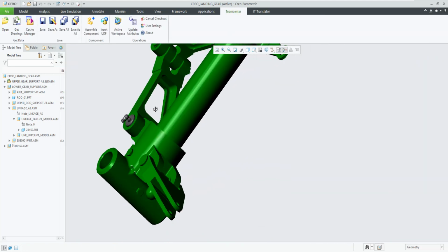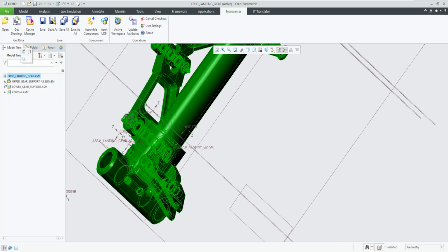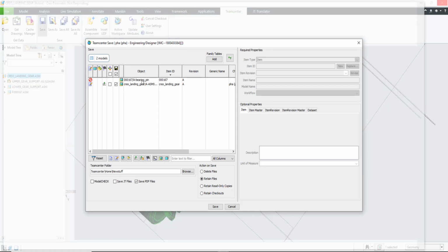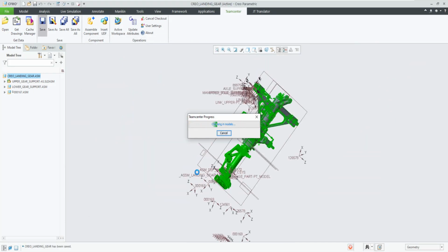To summarize, at this point we have a top-level Creo assembly directly reusing a SolidWorks subassembly and indirectly reusing an Inventor subassembly. When you expand the Inventor subassembly, you can see that all of its JT parts have been converted to native Creo models. Now let's save our work back to Teamcenter, before continuing. The integration will not allow you to save the dynamically constructed Inventor assembly, or its components, to Teamcenter. Doing so would create duplicate Creo datasets under the Inventor item revisions.